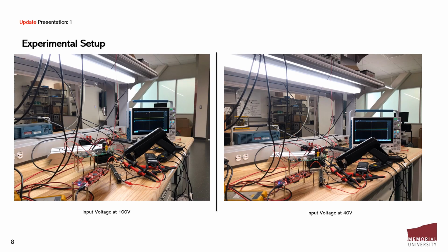This is the experimental setup. Over here we have the DSP board, we have the inverter leg, we have the current probes to measure the output currents, and we also have the voltage probe to measure the output voltage. These output currents and input currents are sensed with a reference. So the output current is being sensed with a voltage reference of 200 volts.